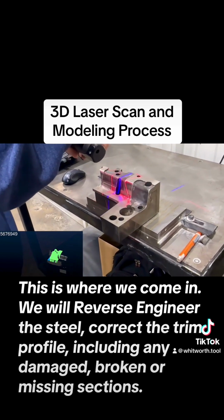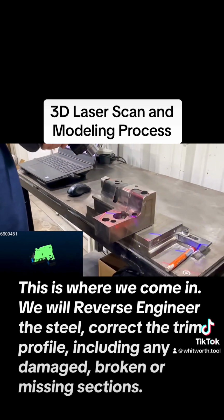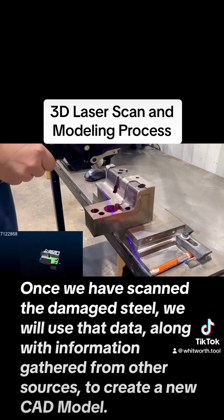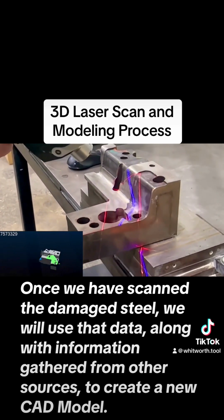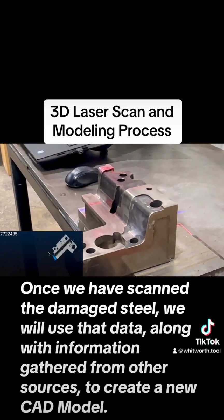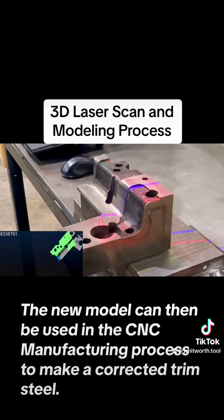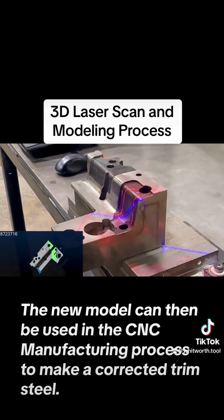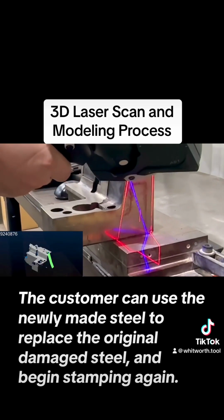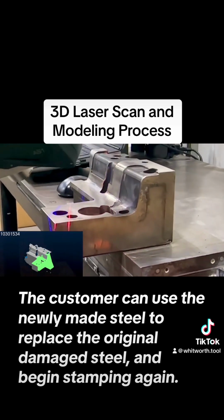This is where we come in. We will reverse engineer the steel, correct the trim profile, including any damaged, broken, or missing sections. Once we have scanned the damaged steel, we will use that data, along with information gathered from other sources, to create a new CAD model. The new model can then be used in the CNC manufacturing process to make a corrected trim steel. The customer can use the newly made steel to replace the original damaged steel and begin stamping again.